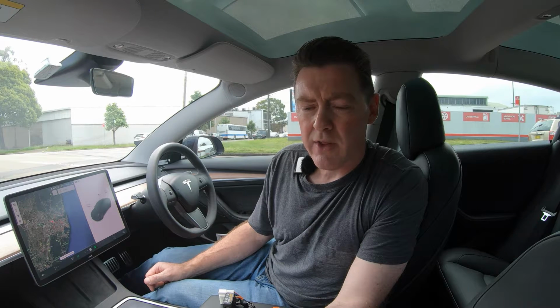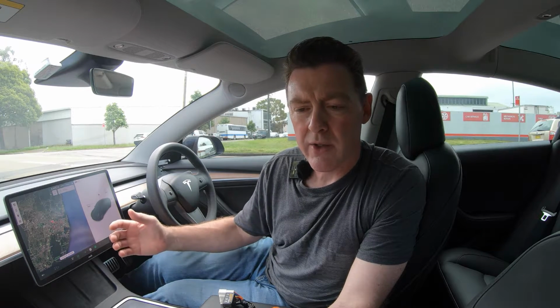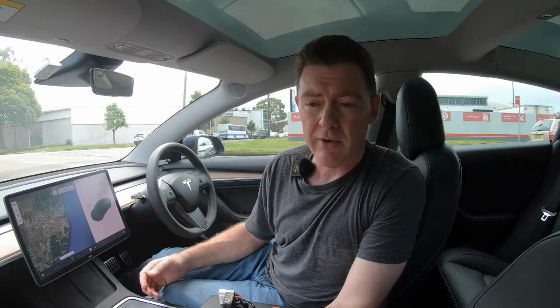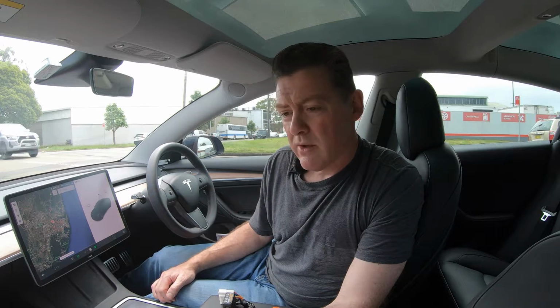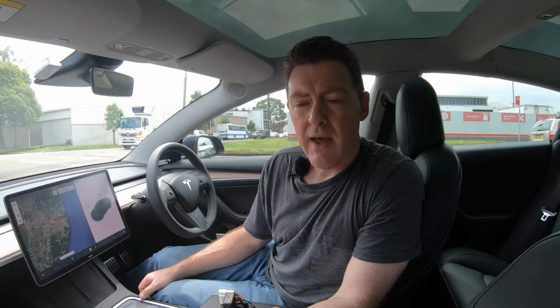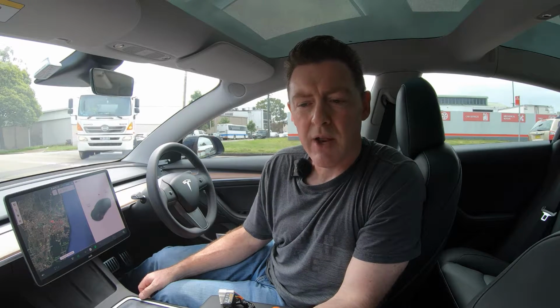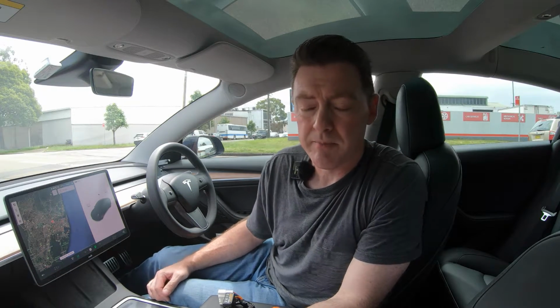So what CAN bus did in the early days was allow the engine computer to talk to the transmission computer and send a lot of information back and forth very quickly. And CAN bus really changed the way things were done. What CAN bus stands for: the CAN part stands for Controller Area Network, because you're basically creating a network between all the electronic components in the car. And then the bus is basically the hardware that allows this network, where the signals are sent over. So it's mostly wiring, the bus part of it.